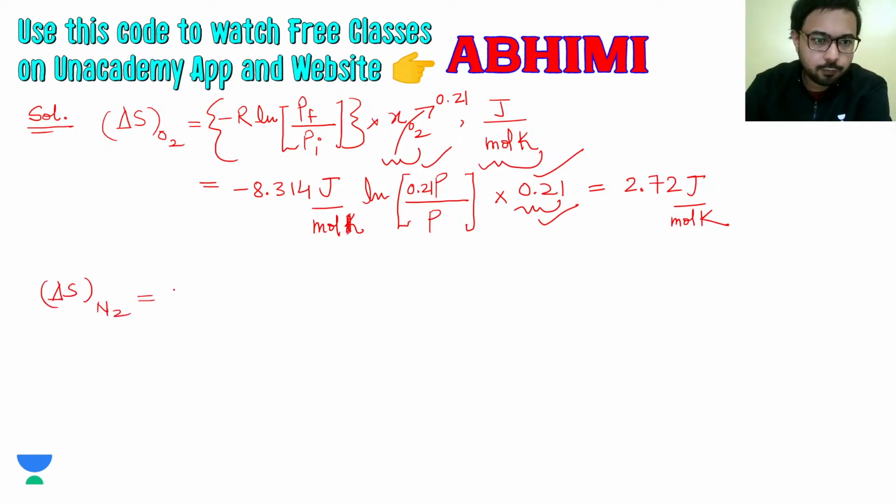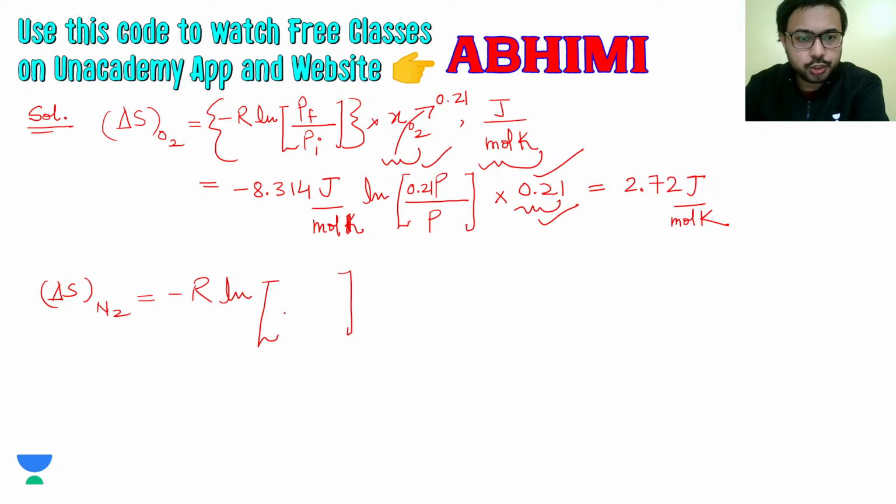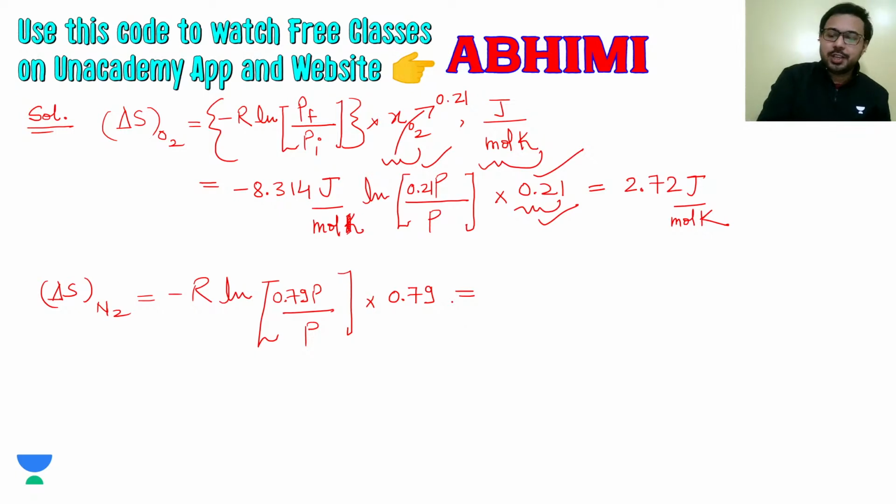Now we will do the same for nitrogen. So minus R ln. The final pressure for nitrogen will be mole fraction 0.79 P. So that will give the final pressure of nitrogen. Initial pressure is P only, and we will multiply it with mole fraction, which is 0.79. So this will give us the value of change in entropy for nitrogen gas. So it is coming out to be minus 8.314 into ln 0.79 into 0.79.